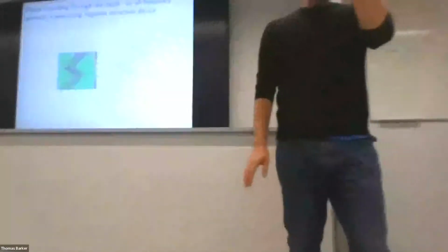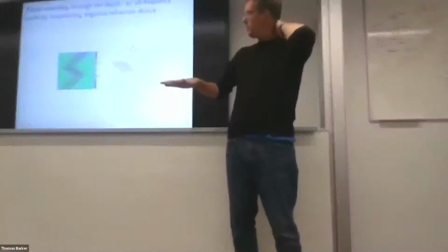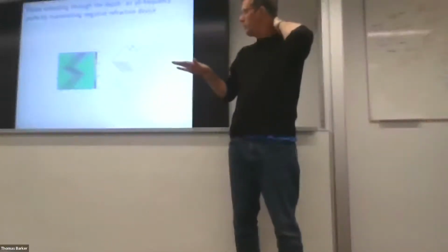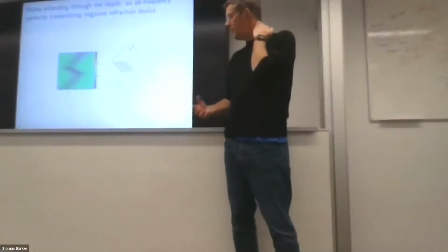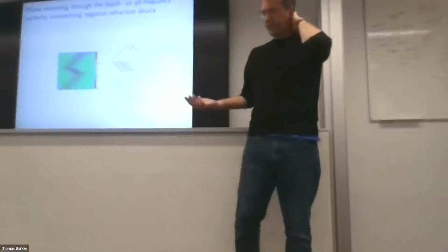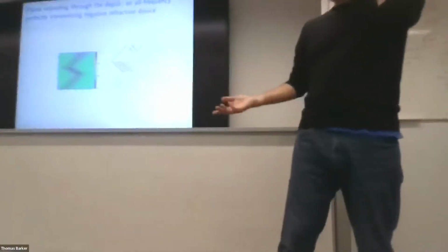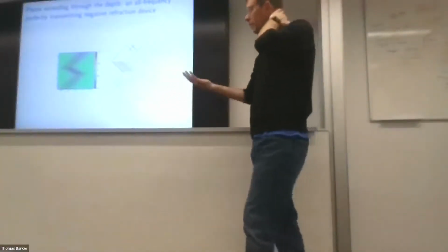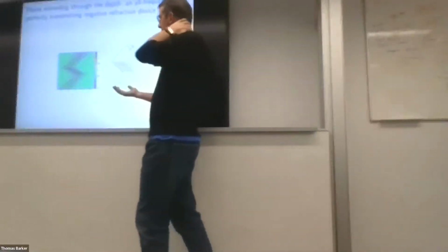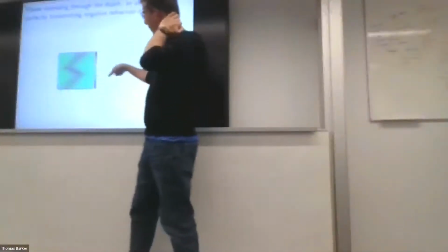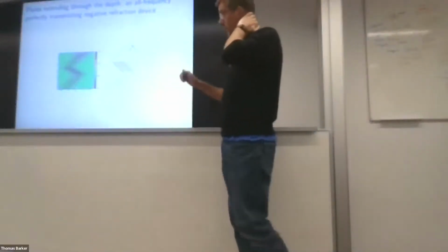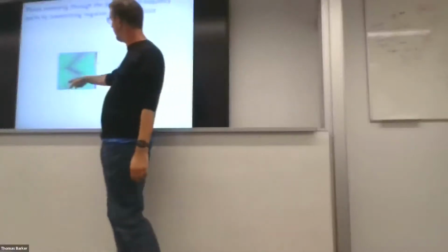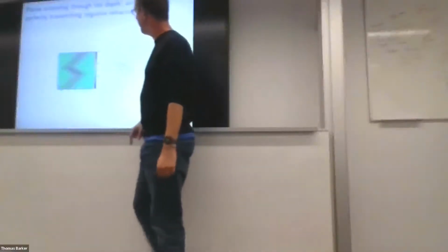I'll just mention this because this is all to do with plate arrays that don't protrude all the way through the depth. If the plate array protrudes all the way through the depth, then your life becomes a lot easier, because then you don't have to use shallow water theory anymore. You can use full potential theory, and you can take out this cosh dependence and give yourself a two-dimensional problem. Okay? And in fact, this piece of work preceded the stuff that I've just shown you about the bathymetric plate arrays. So this again is a similar situation showing negative refraction.